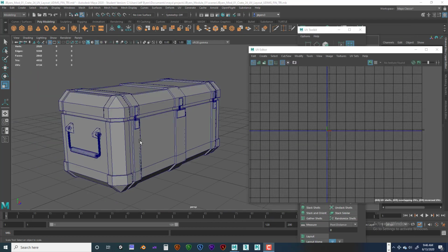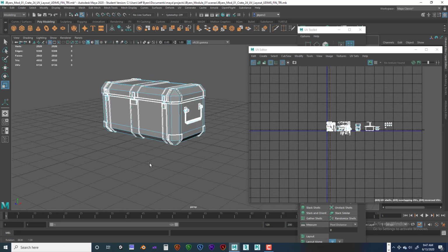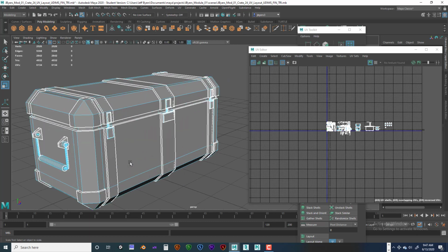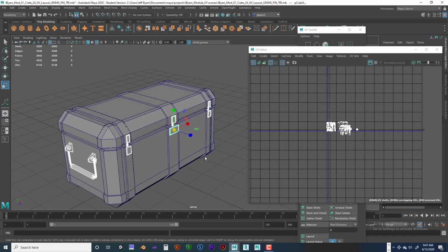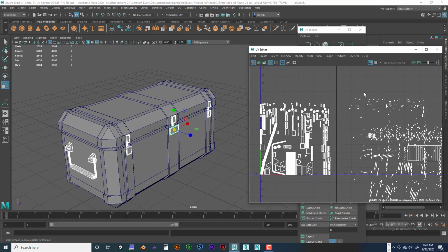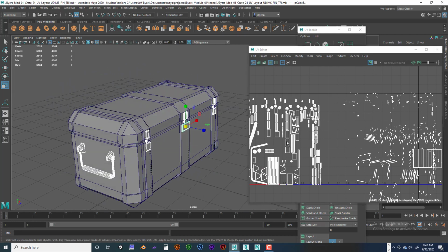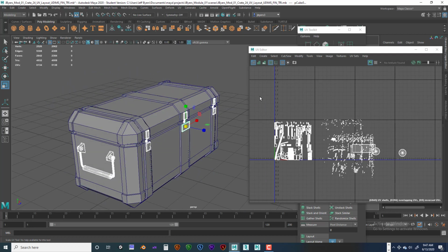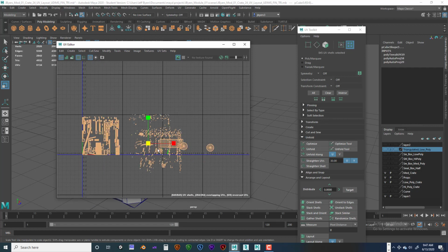Okay, I wanted to show you this issue I was running into. So just to let you know where I'm at, I'm going to select this object here and deselect this object, and let's go into object mode. So I got all these pieces set up. Okay, so I got this error. It wants to lay out the UVs, but I got this non-manifold geometry issue. To lay out UVs, let's go in here to UV shells. It doesn't like non-manifold geometry at all.